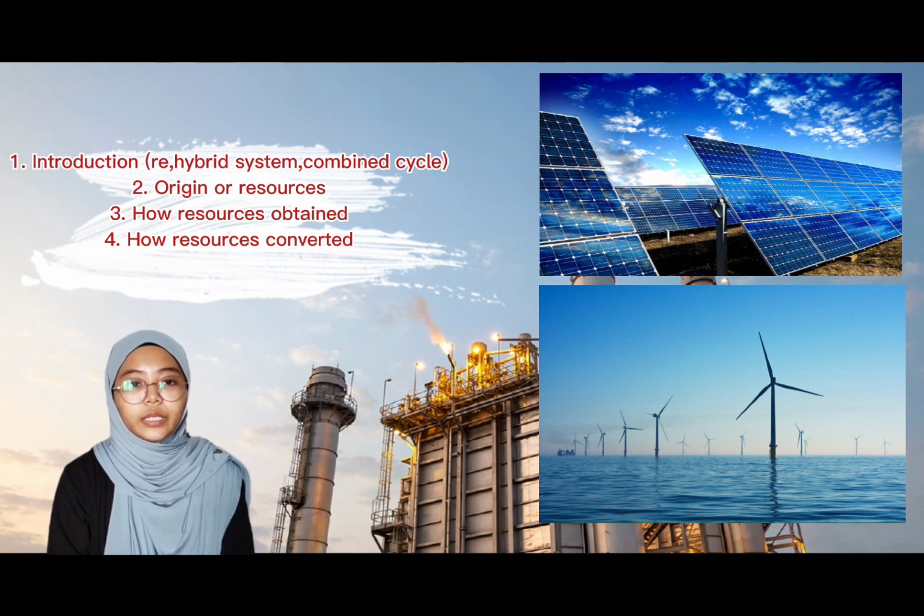The conversion of wind energy into electrical energy. The first step is that the wind turbine propellers are rotated by the wind. The propeller spins the rotor, which is connected to the generator via a main shaft. The mechanical power flows into the generator, which converts the power into direct current electricity. An inverter is required to convert DC electricity into AC electricity.